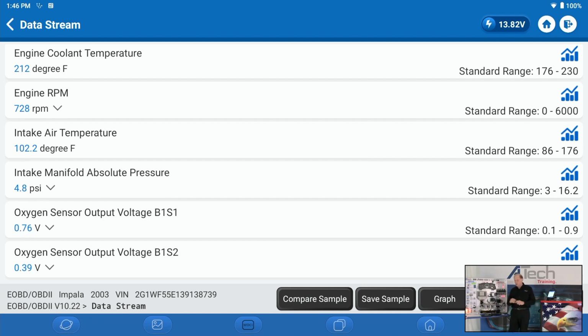Now, if I'm looking at the board, my O2 sensor on this little bar graph over here is going up and down. Notice it's going up and doing its job. Look at my rear O2 sensor, it's pretty well fixed. You usually want these things to go somewhere between under 200 millivolts and above 800 millivolts. I'm not always going above 800, but I'm there. Now, if I speed this thing up a little bit, when I speed it up, it went lean because we sucked air in it.